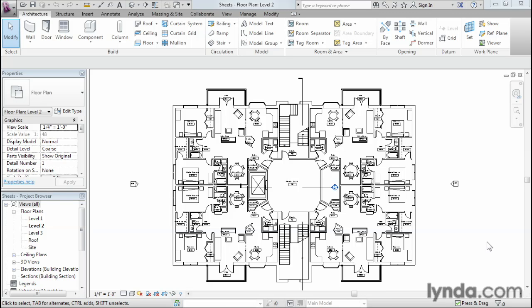So I'd like to look at some of the tools that we have available to us, and I'd like to start with the line weight and scale display. AutoCAD does a terrific job emulating the traditional drafting experience, but it's never really done a terrific job at emulating line weight, particularly on-screen display. We've always had to wait until we printed the drawing in order to see the final line weights, and we had to interact with a fairly complex collection of plot styles and color mapping tables and other mechanisms in order to get the line weight display that we want.